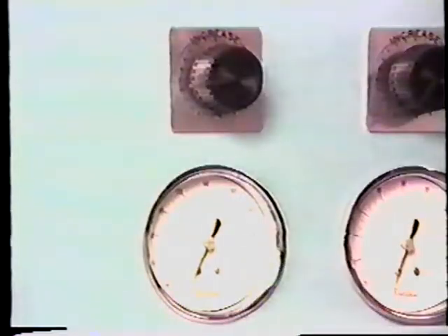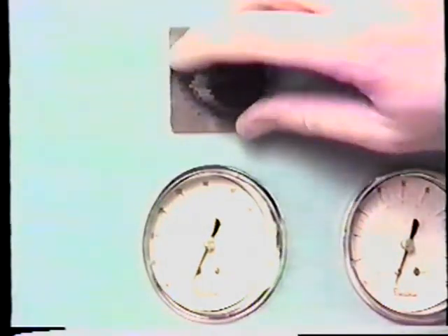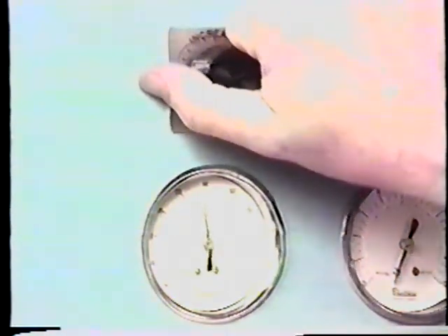To set a switch, first apply the desired switching pressure to the diaphragm. Then turn the adjustment on the appropriate switch until it is activated. Repeat this procedure for each switch to be used in the controller. The pneumatic step controller can be ordered in standard configurations of 4, 6, 8, 10, or 12 single-pole double-throw switches.